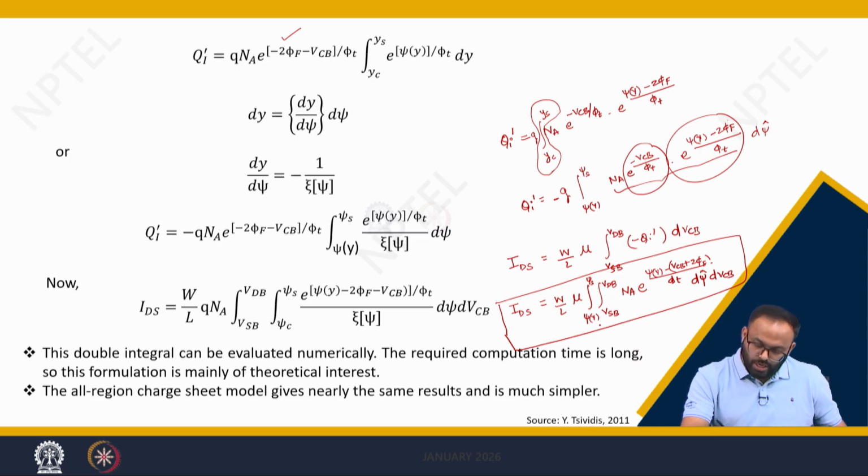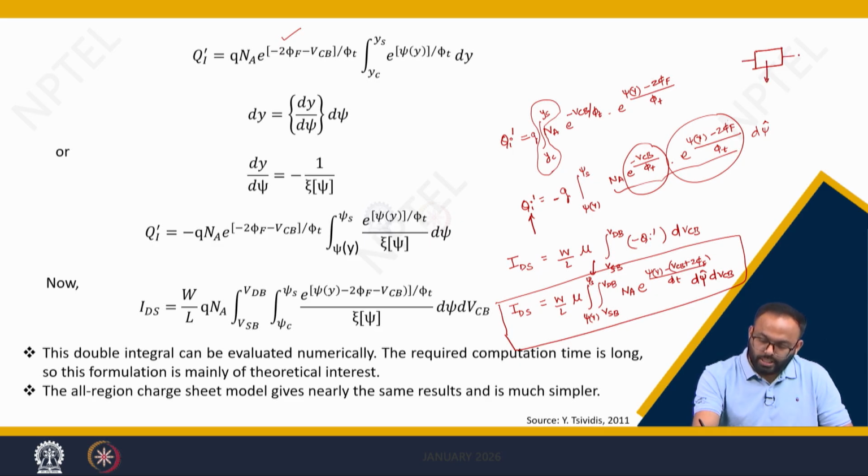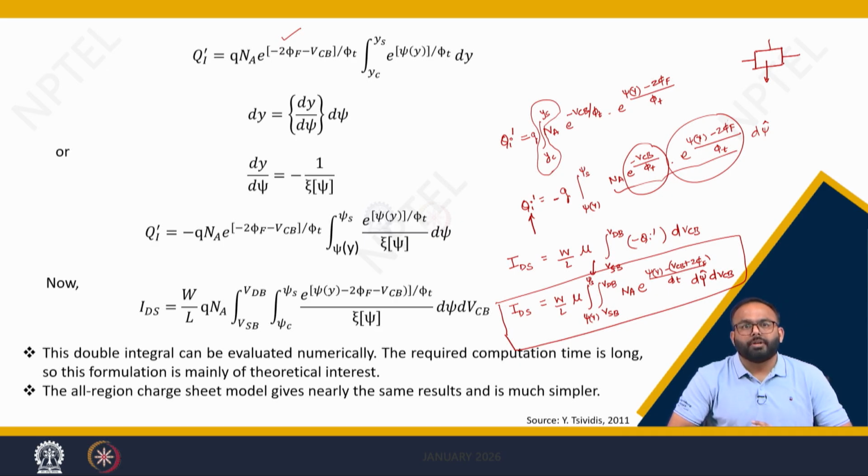Instead of playing with the inversion charge and the surface potential, can I not represent my current equation in terms of terminal voltage, which is more important because you are going to implement these devices in circuits, and in general the circuit designer considers this device as a black box. So if you are considering the device as a black box, then you have the terminal voltages in your hand to play with, and hence the prime goal is to represent your MOS analysis in terms of terminal voltages.